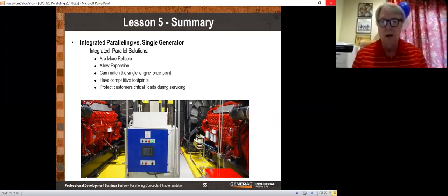And we basically go out, we hook our laptop into the thing, we take a look and see if we've had any faults from the past. We, again, check things like batteries and battery chargers and block heaters, and there's, like in your car, a number of checks there, but we don't actually change the oil or anything like that. And then 6 months later in the year, we would go ahead and change the air filter, change the oil filter. If there's any water, let's say, in any of the fuel filters, we would drain those,